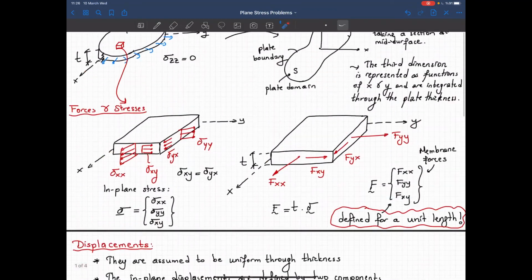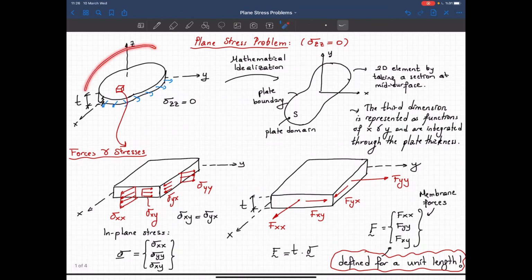what we did. So here our aim is we have a 2D truss member. In other words, it's called a membrane element, or we can just say that the membrane element resists axial forces in two directions. We call these directions the local X and Y directions. And we say that we'll consider this as a plane stress problem. So we are assuming that the stress in the Z direction is equal to 0.